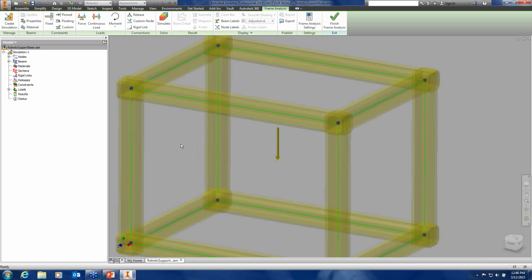And so it's projected those and it's connected them together. Another reason why I like to do it like this before you clean it, before you miter it, before you do some trimming, is you'll start getting a lot of extra nodes that way. And to me, that confuses me more than it maybe confuses the program. But it confuses me, and sometimes it might make a node dominant that maybe I don't want to be dominant.